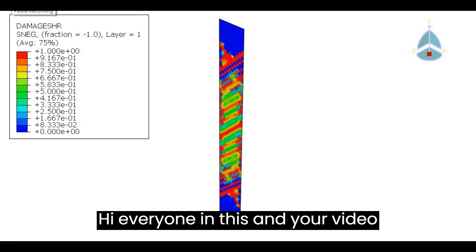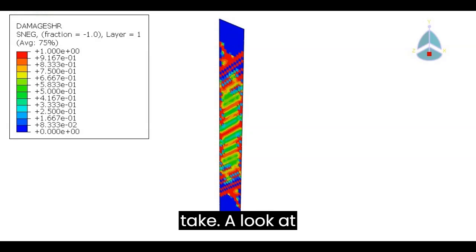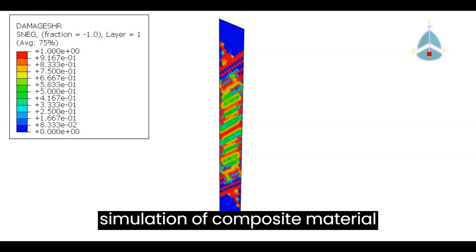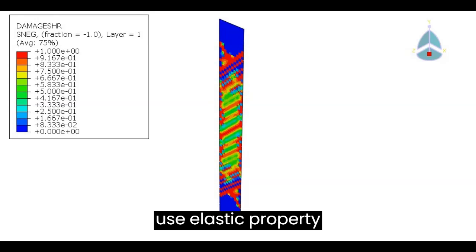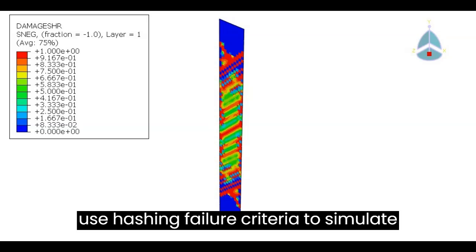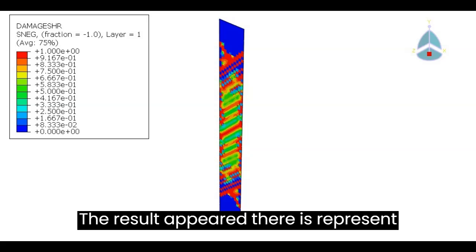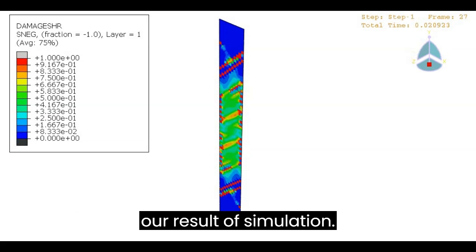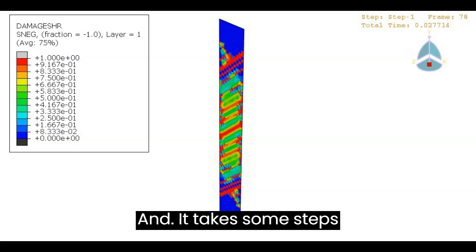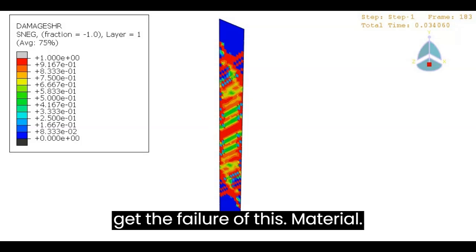Hi everyone, in this new video tutorial about Abaqus learning, we will take a look at simulation of composite material using Abaqus. In this video we will use the elastic property of composite material, and also we need to use Hashin failure criteria to simulate the failure of composite material. The result appearing there represents our result of simulation, and it takes some steps to create this model and get the failure of this material.